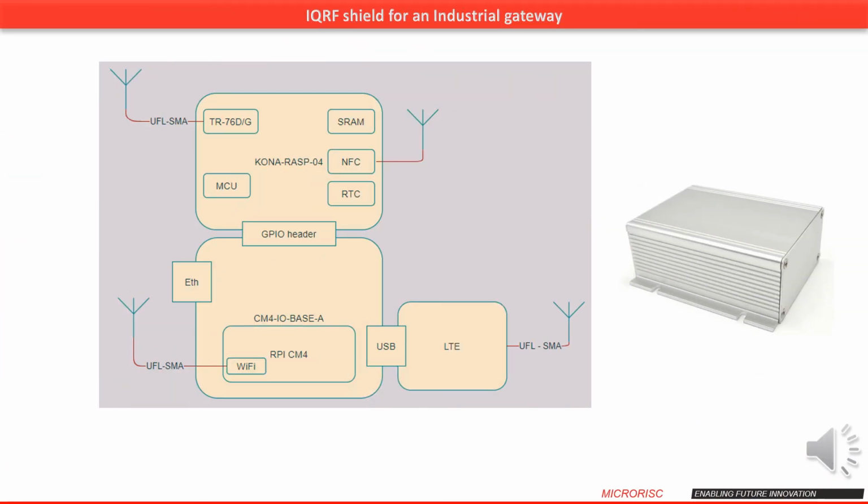Due to the need for use in industrial environments, there is a requirement for use in a wider temperature range. For such systems, it is better to abandon the cheaper Linux machines using SD cards and replace them with a machine with integrated eMMC flash, such as the Raspberry Pi Compute Module 4. Since this is a compute core, a custom motherboard with the peripherals needs to be designed for it, or an existing commercial solution can be used.